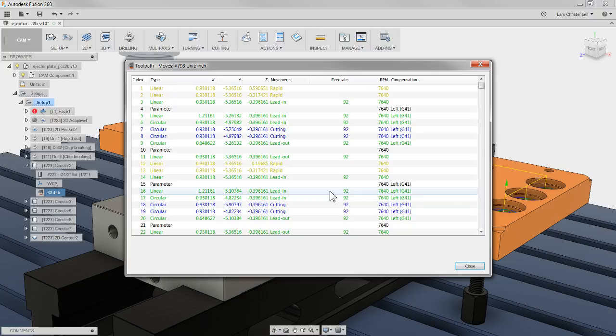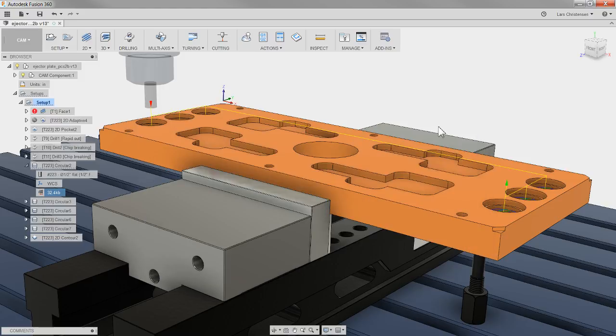You know, and then you're standing looking at the screen and you're looking at your coordinates. Going in here and just clicking here is a quick way to cross-reference: are these the right coordinates I see on the machine versus what I see on the screen on the control versus what I see in here. So it's a little hidden in here, but I think this is a super duper little function to have when you are in those troubleshooting modes.